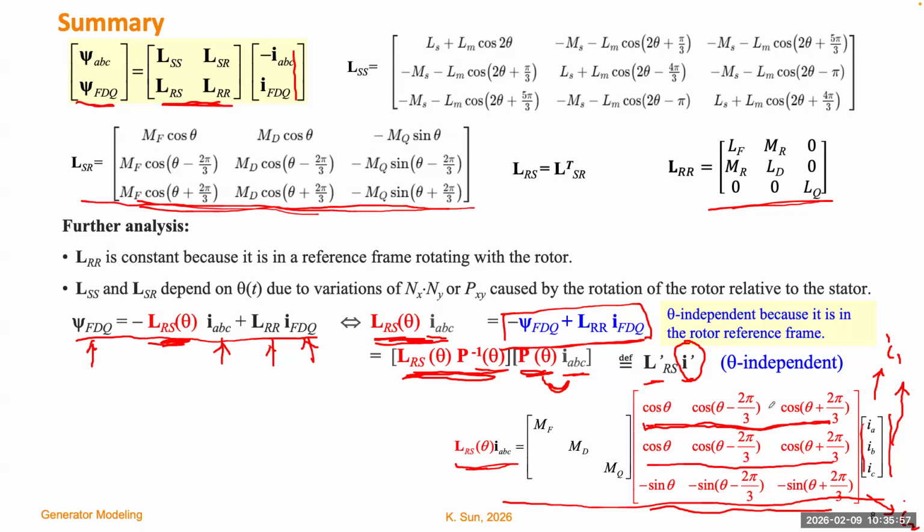But one problem of this definition is that originally we have three currents, IA, IB, IC. They are actually independent in any condition. Only in normal condition do we know IA, IB, IC have the same magnitude but 120-degree displacement. But for fault conditions, IA, IB, IC may not depend on each other. So we still need to introduce another current element for the three dimensions, right? So we can create another element, I3. We simply define I3 to be their average, the average of IA, IB, IC. So basically just the current going to the ground.